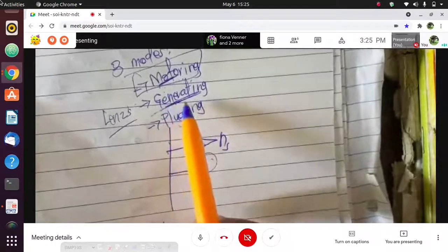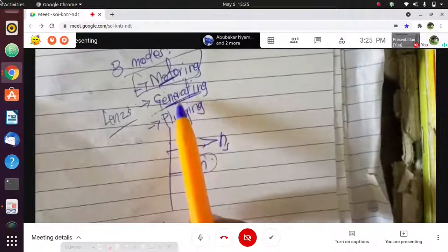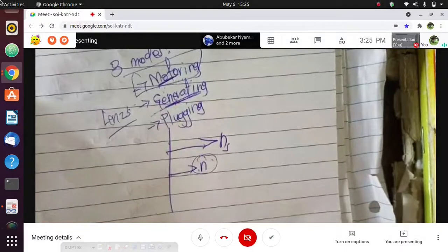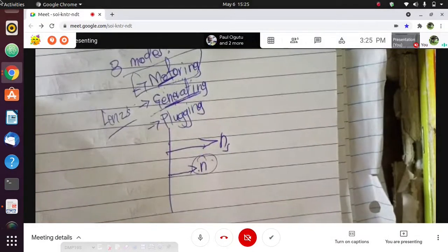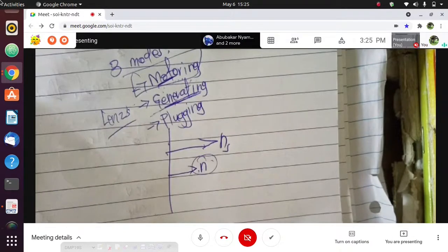Suppose we are running this induction motor with a variable frequency supply, meaning that I can increase or decrease the frequency at which I'm supplying my power. When I increase it gradually from 0, the speed of the motor will increase up to steady state. So when I'm feeding my motor from a variable frequency supply, the speed will increase. We do this to control the speed. Now, to stop the drive system, to stop that induction motor, the speed is gradually reduced.